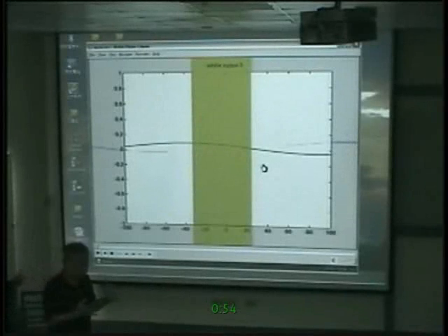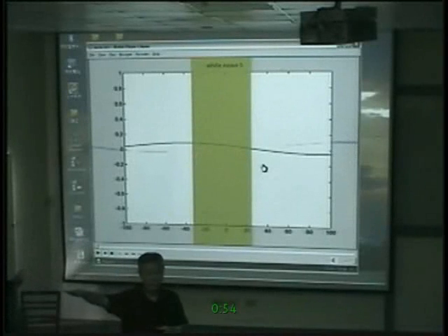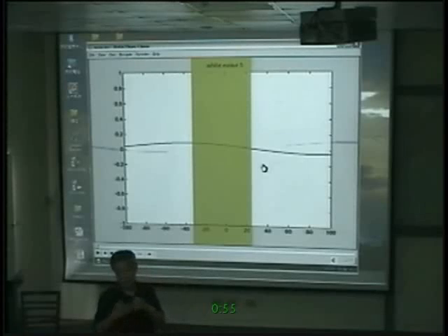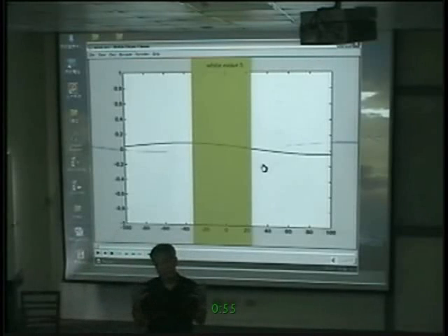Both the delta function and noise have a white spectrum. The spectrum is flat: the amplitude is constant, the frequency is different. So it's all white spectrum. One is delta, one is random noise. What's the difference? The difference is phase. In the Fourier spectrum, the phase information is not there. If you do the Fourier transformation, the phase is there. You can use the imaginary and the real parts and recover the phase. But using Fourier spectral analysis as we know it, derived from Wiener-Khinchin theory, the phase information is lost. So it's incapable of separating the two.